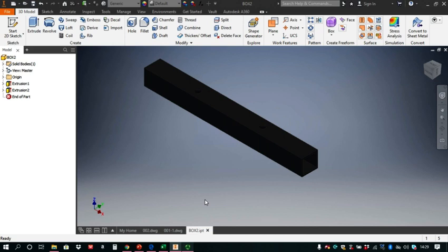And that's why your drawing order is important. You do not want to be drawing the base profile and the base material any more than you have to. So if you can group all your box sections together, all your angles together, all your sheets together, and do them in an order that is very easy to adapt one to the next, you will save yourself quite a bit of time.